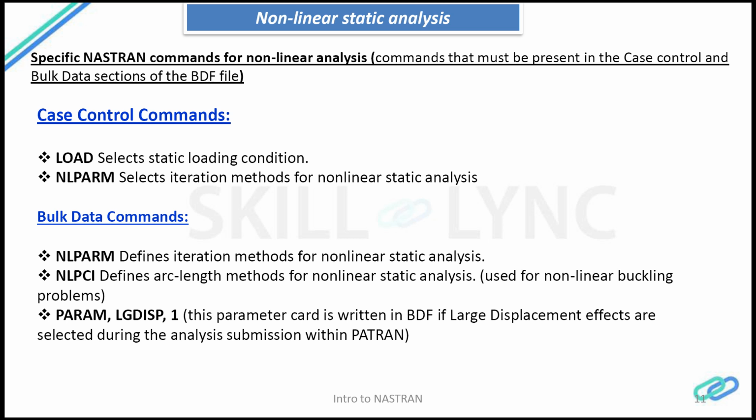The famous one for the nonlinear static problems is the Newton-Raphson method, which is widely used within the engineering community. And then in the bulk data section, there will be a corresponding NLPARAM that specifies the time step or the incremental steps, in how many increments the load has to be applied. And the NLPCI command is for the arc length methods, which is typically used for nonlinear buckling. And the PARAM LGDISP, which stands for large displacement. This is used for large displacement problems or geometric nonlinearity problems.